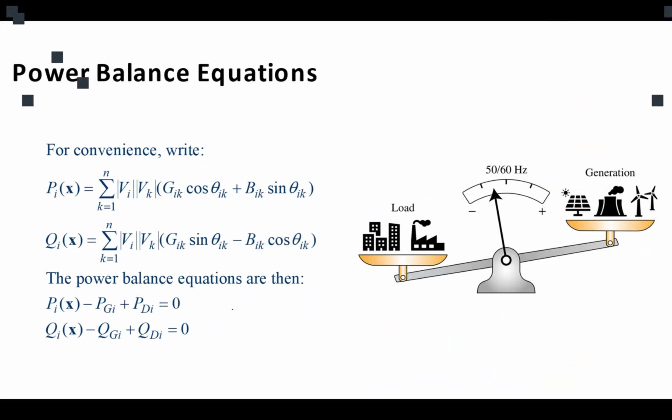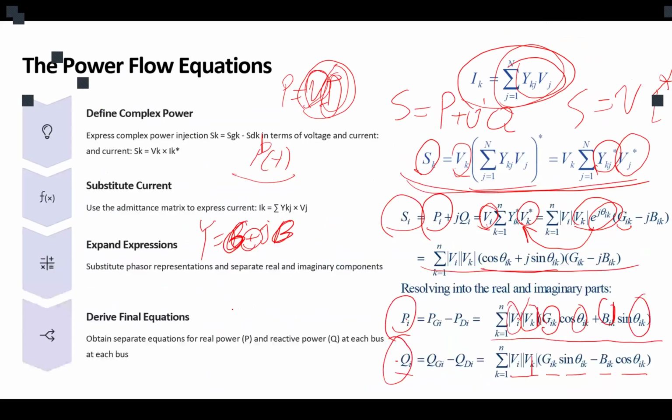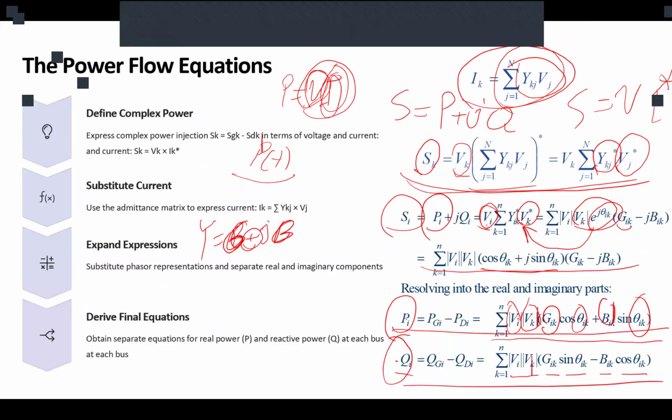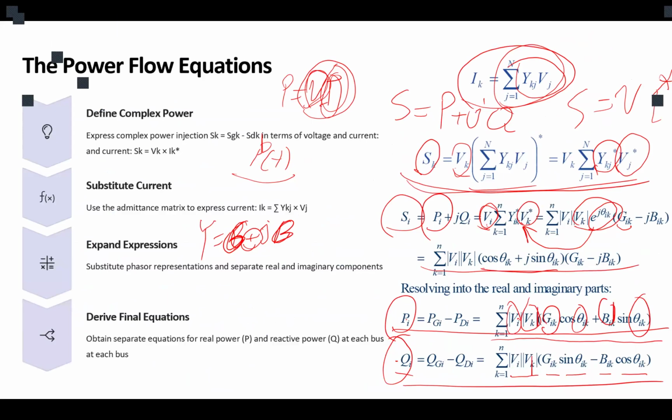No. Okay, before I move on, this is the formula for P, and this is the formula for Q. Before the midterm, I mentioned that when we want to control the inverters, controlling the theta would make the active power control, and controlling the voltage would make the reactive power control. You remember that?